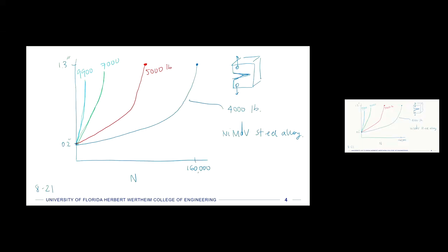And we can look at this graph and say, okay, I see some different regimes here. The thing did not fully break, but there's maybe 2 regimes in each one that look like stable crack growth. If I look at this, I can say there's a lower slope regime and then a higher slope regime. And I did not write what the y-axis is, but it's crack length in inches. It's probably pretty apparent.